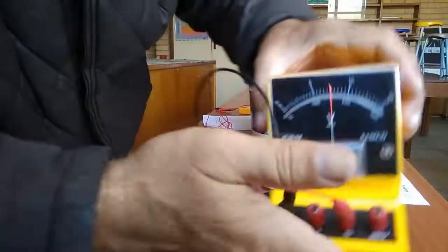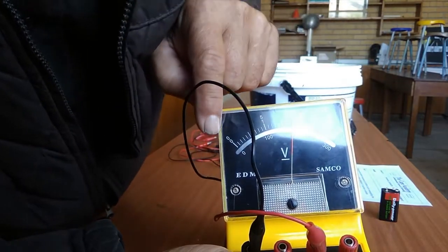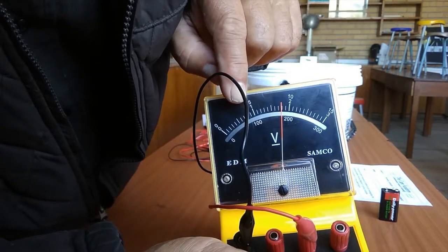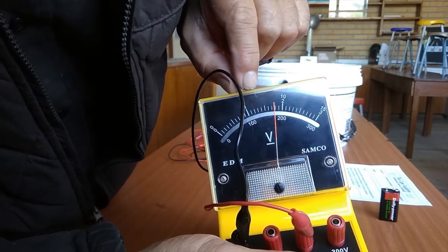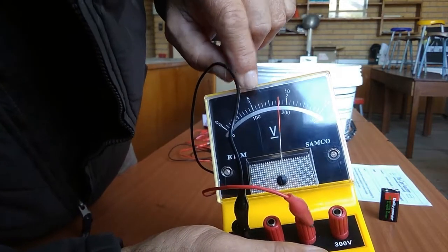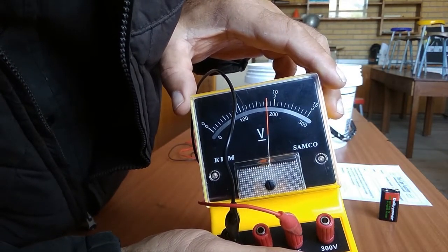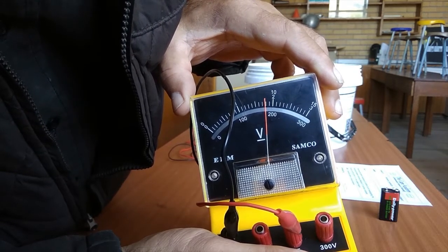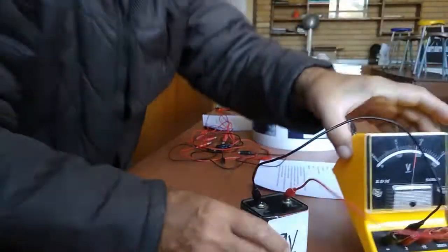Now, do you see on the 15, we're reading on the top scale. So there's 5, 10, 15, and we see that every 2 units is going to be 1 increase in volts. So we see it's 2 from the end. That is actually just a fraction under 9 volts. It's about 8.9 volts. So it is almost a 9-volt battery.